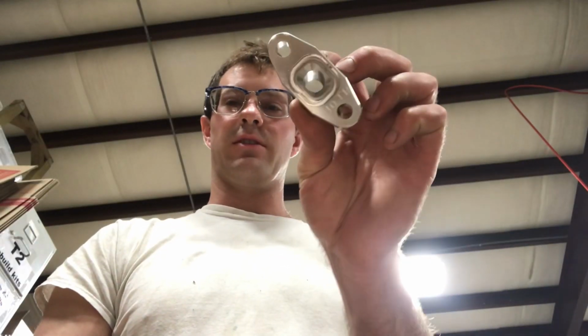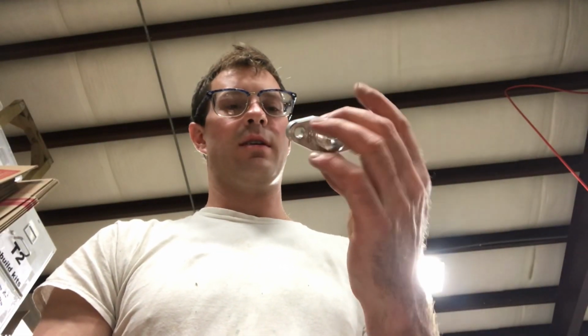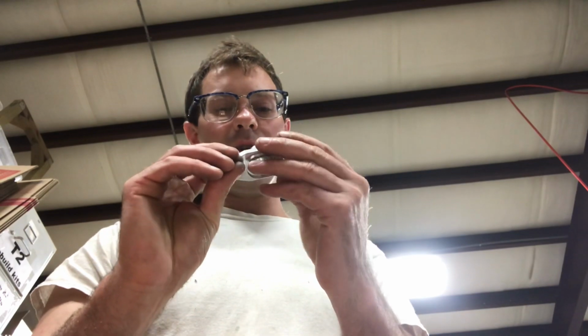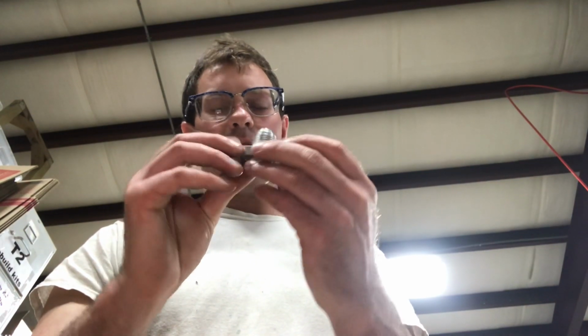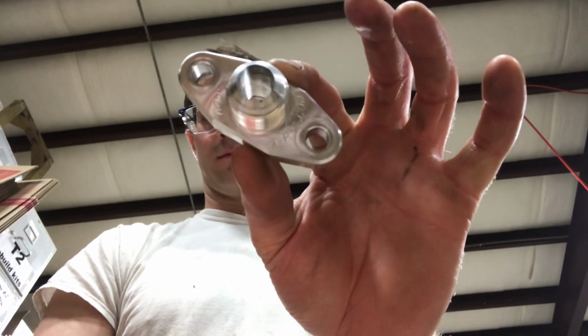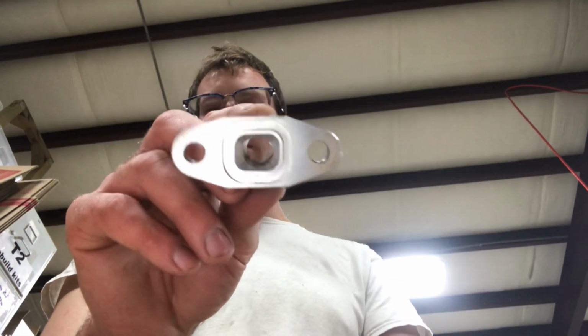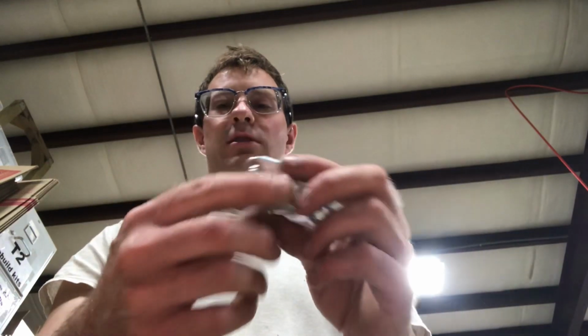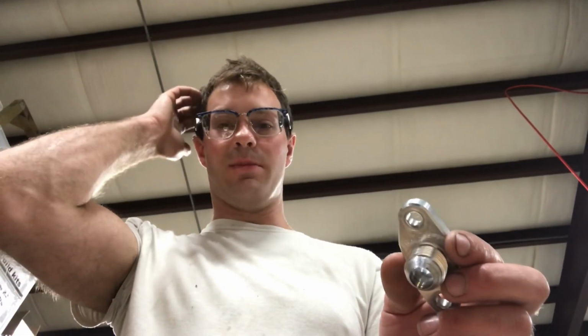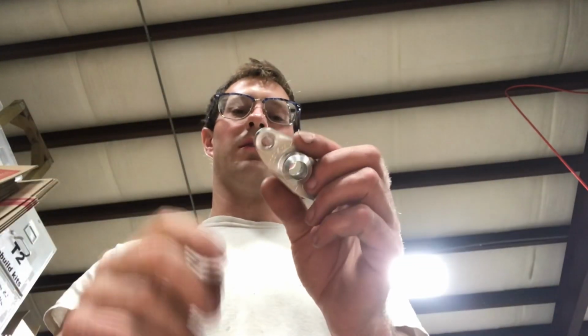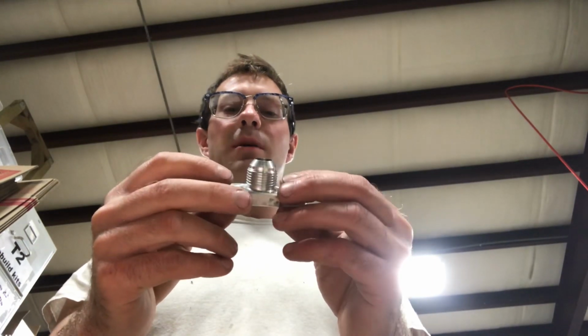I'm going to show you how to fix this turbo drain permanently. So this one, it says arz.com on it. It's flared to kind of help with the drainage, but it still has a problem. The main issue is this guy has this on a really big turbo that requires a lot of oil, and it's just not able to flow properly.